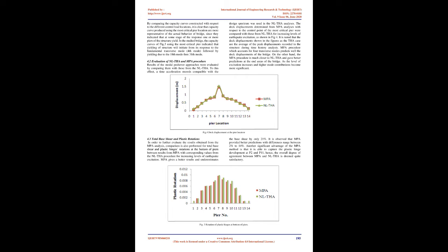A design response spectrum should be available in order to perform pushover analysis. This bridge is to be built in a seismic zone with an acceleration coefficient of PGA equals 0.3 g.